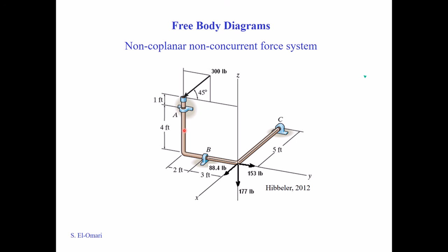In 3D, if you review the table given in any textbook about 3D support reactions, there are different types of supports. Again, the important part is always looking at a support and thinking what direction it will prevent motion or rotation. This type of support is called a journal bearing.